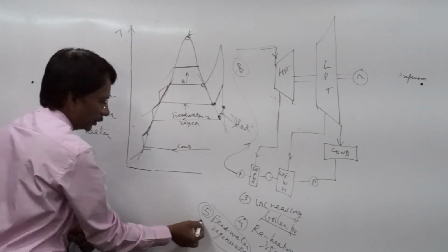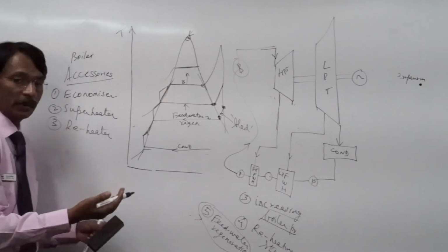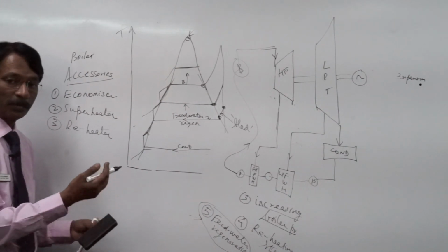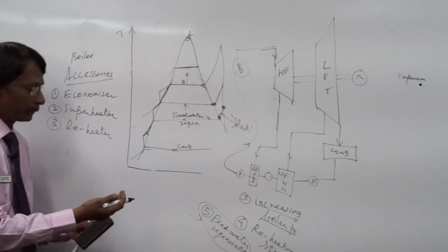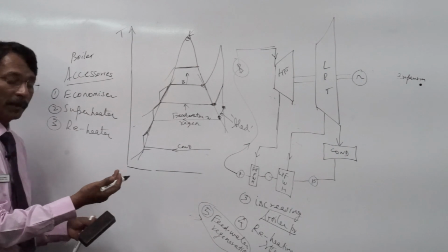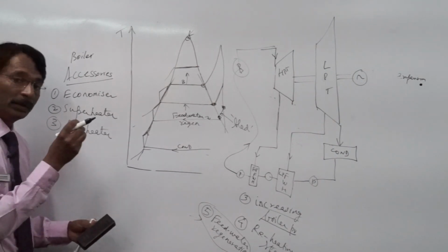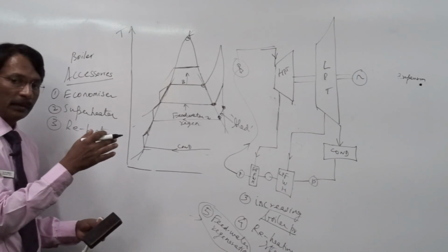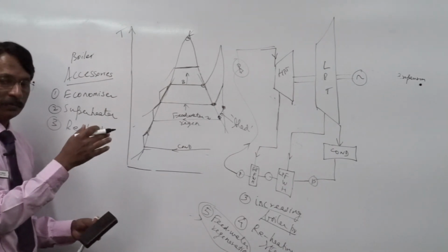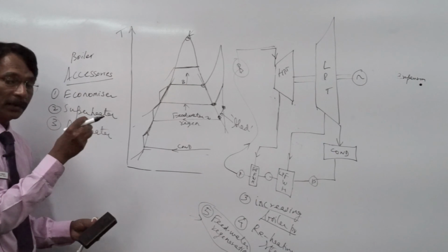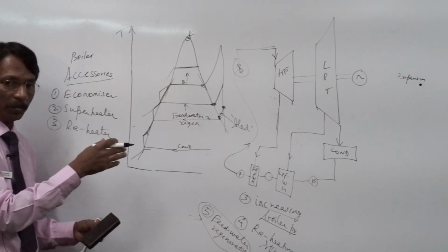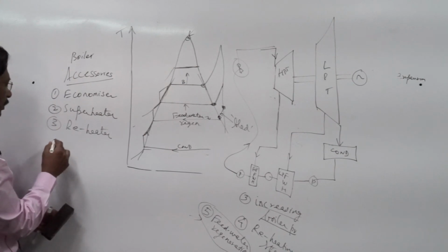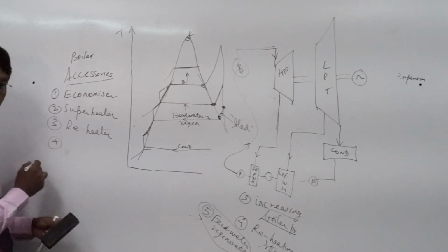And this means I am enhancing or increasing the sensible heat of the feed water, and I am able to spend little fuel only in the boiler. So, my coal which is burnt, the heat that is required to be given in the boiler for the feed water is reduced, and I am able to get greater efficiency.